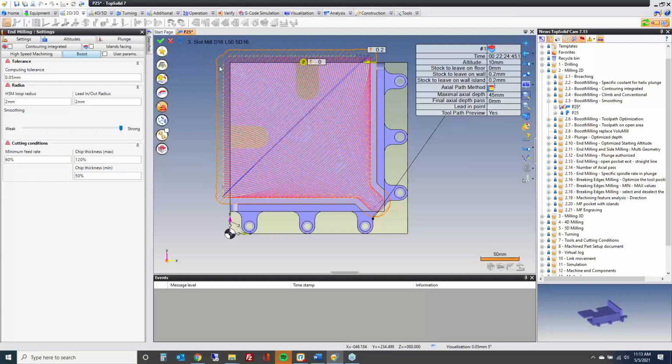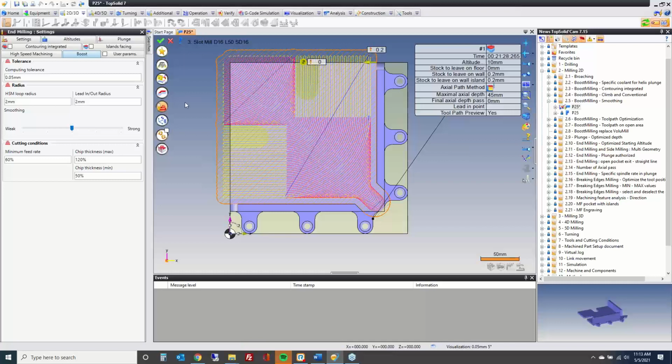Now we switch to concentric circles to make big sweeping movements, and you have fewer turnarounds. You can back this off a little bit, and you can play with how much smoothing you want. So here you can see big sweeping movements. Then we get into here where we have more linear, back to big sweeping, into linear, and so on.